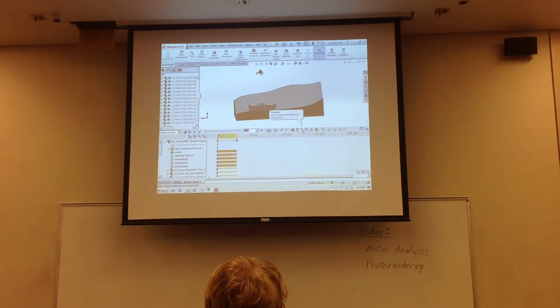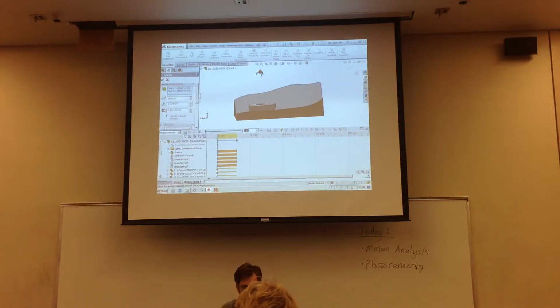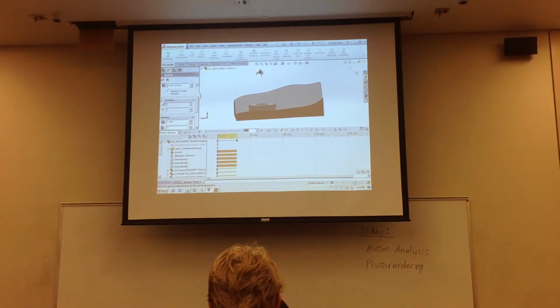Okay, but because most springs have inherent damping, we don't have to add a separate shock absorber using this button. We can just go back and edit our spring definition because it's got a section in it right here for adding damping. So we click the checkbox to turn on the damper, and again, you can choose a linear or a nonlinear damper.